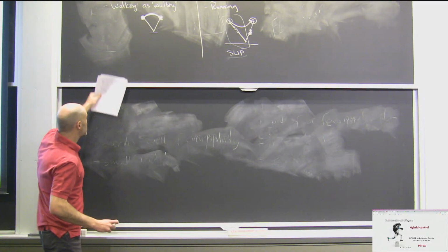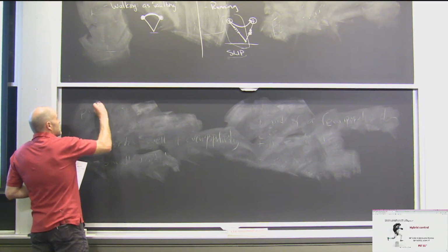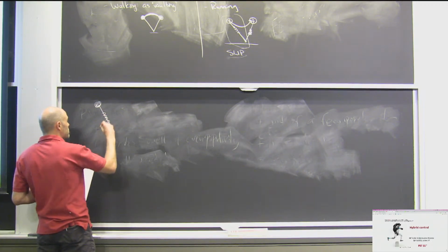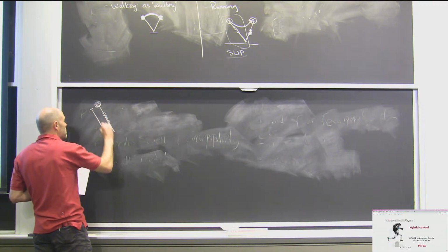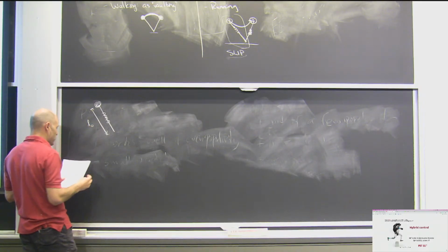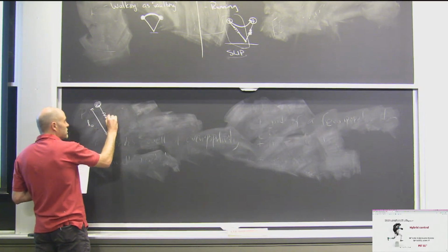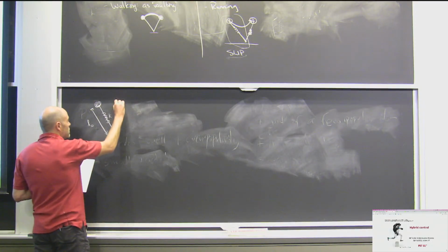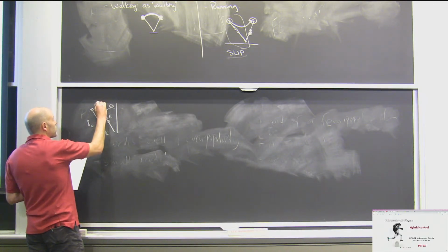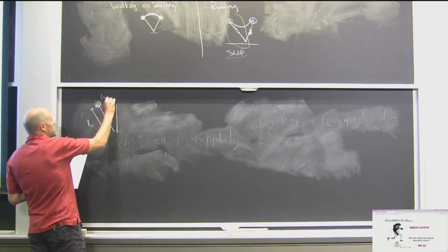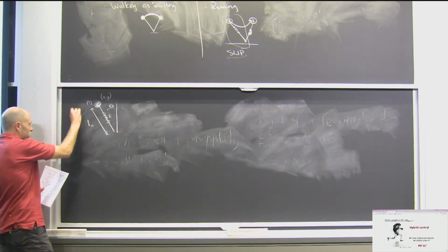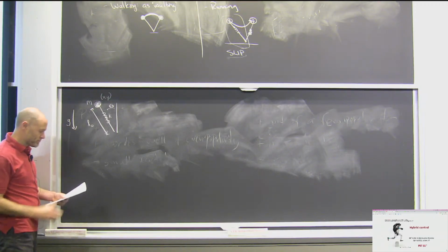So this spring-loaded inverted pendulum has the same characteristics as our simple models here. So I'm going to give it a rest length L, call it L0 for the rest length. I'll give it a spring constant K. Going to parameterize it with an angle theta. Call the XY position of the point mass M. Gravity G. Okay.